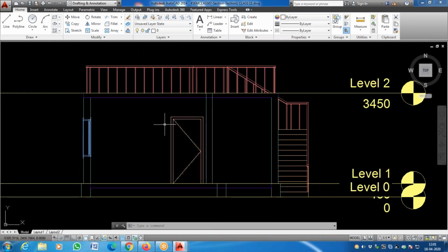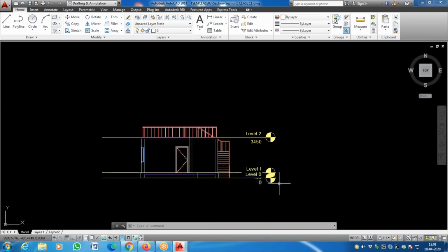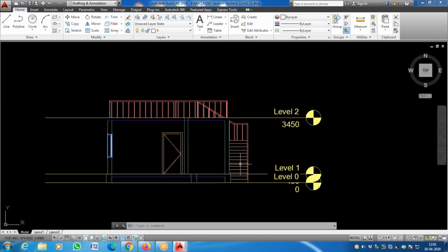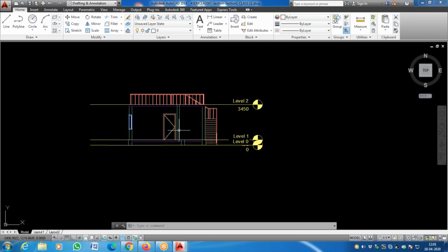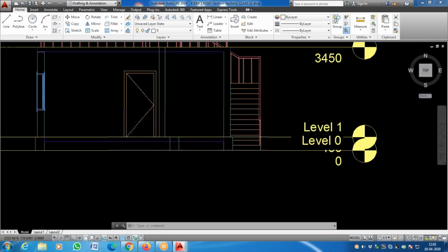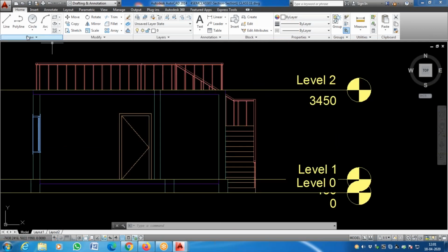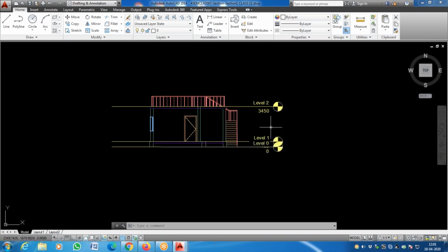So please use this at least in your submissions. You can do something in Revit which is hard for you to conceptualize, but you have to do it properly in Revit. That is another catch. You have to do it properly. Bring it here and export into AutoCAD, and then maybe you can color them or compose them, if you feel composing them into the sheet in Revit is difficult, also for your convenience.